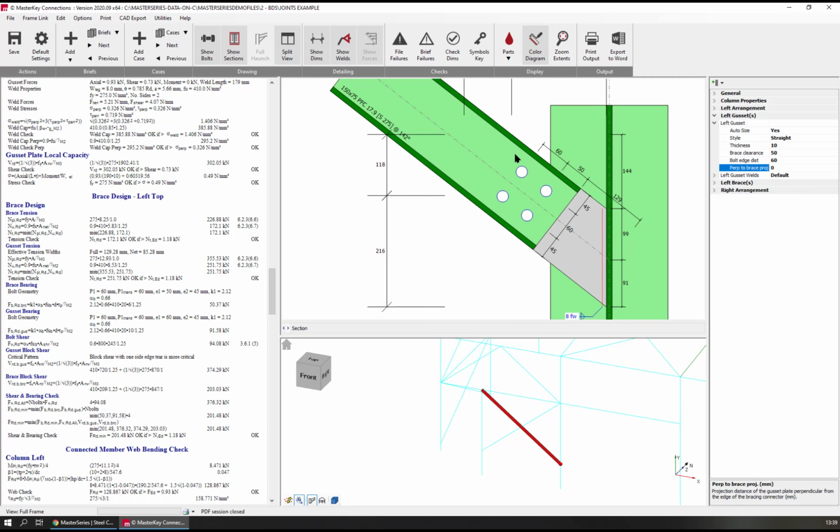It also, from a design point of view, doesn't really tell you where the plate stops. So I always like to see them at least 5 or 10 mil proud, so that you know it's there. It also will help with the length of the welding, which can also solve problems. So you have full scope over that.